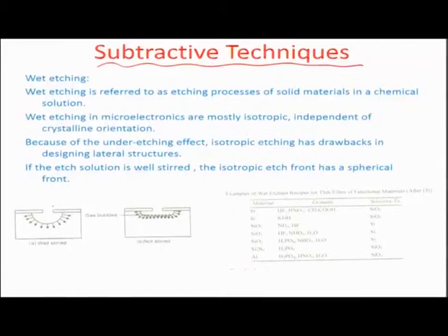Typically you can categorize the wet etching techniques into either isotropic form or anisotropic form. So, in the isotropic section, we mostly discuss homogeneous material etch processes. Etch rates are similar and not a function of the direction in which etching is taking place. On the other hand, the anisotropic chemistry depends on the direction it takes. And so, typically what we do in microelectronics is shield an area and then create a small window or a via through which you can then take the etchant.